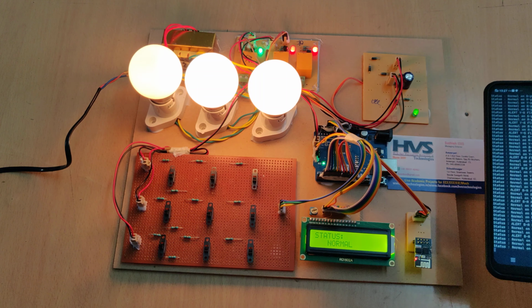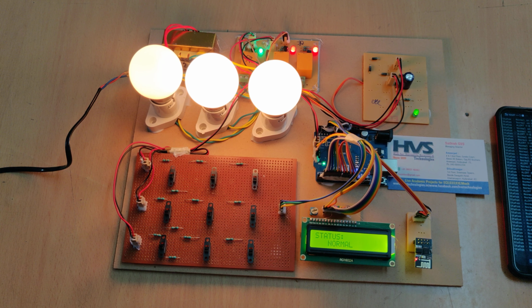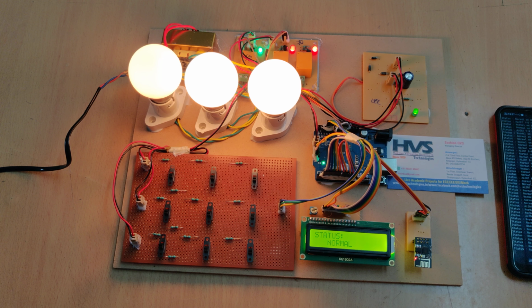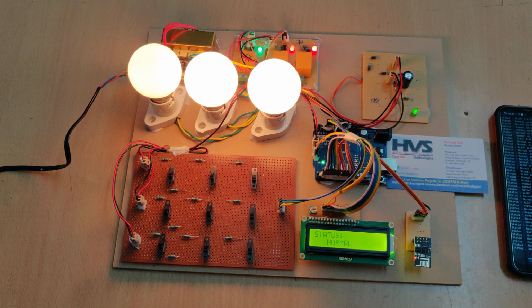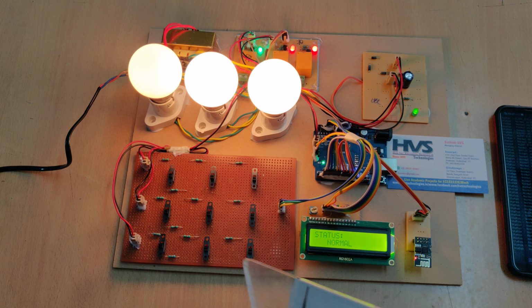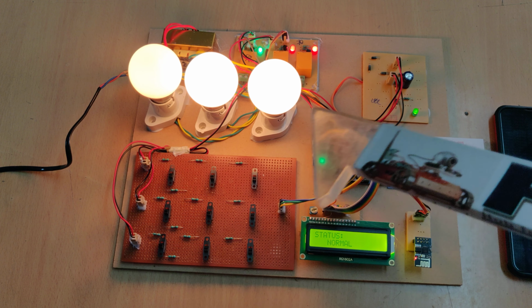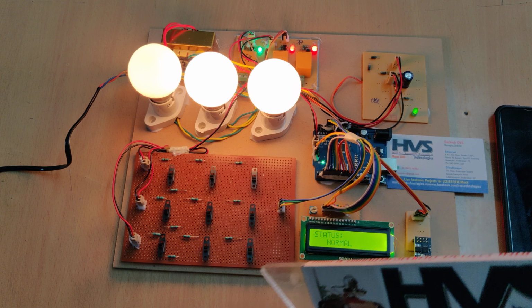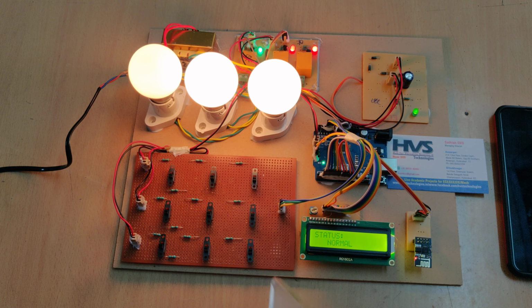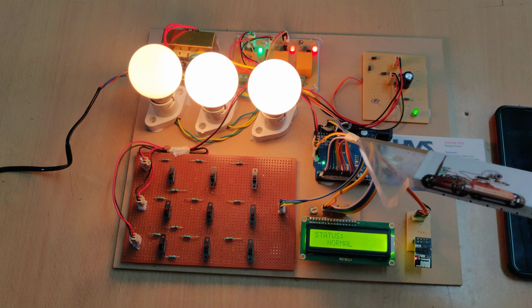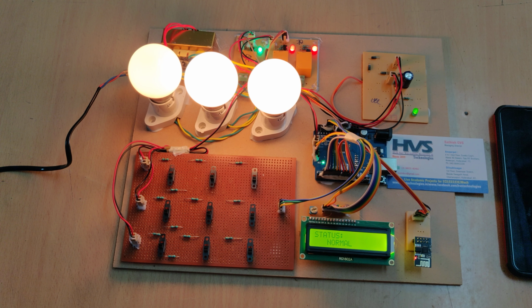So this is the main useful function in underground cable faults. Why? Because if any underground cable fault is detected, then instead of digging throughout the length of the wire, we check the drop voltage based on the length of the wire. Whenever a short circuit happens, the system will check the dropped voltage and provide us the estimated distance, so that it is easy for the workers to dig at that particular point and repair the fault. Thank you.